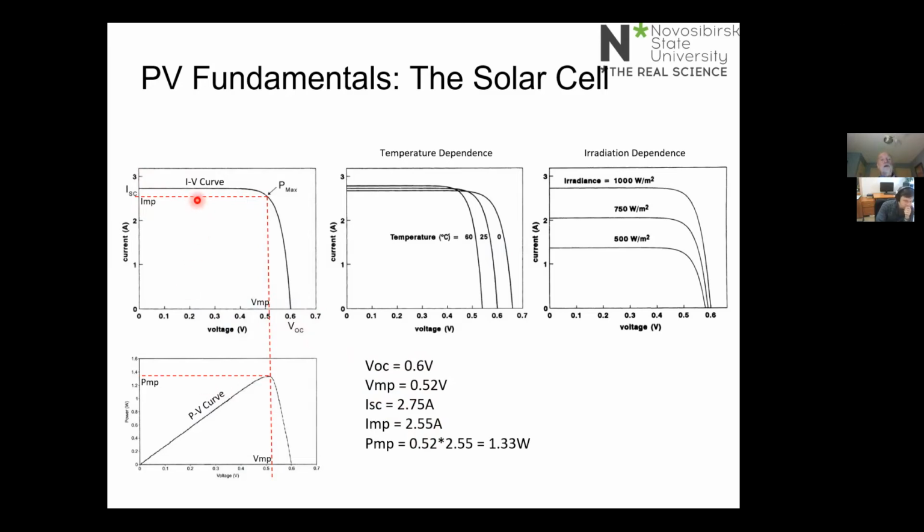If you turn the IV curve into a power curve, and power is simply I times the voltage, then a PV cell will have a power curve that looks like that. And where you want to be operating is at this point here, because this point, MP stands for maximum power, is obviously the point that is giving you that maximum power.